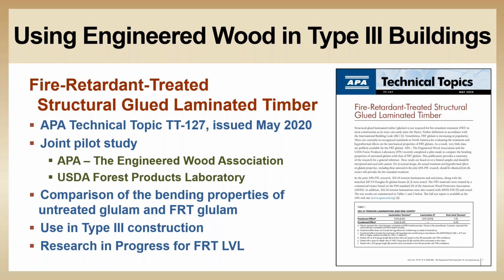Additionally, I'll note the test of FRT LVL is currently in progress. So if you get a request for FRT LVL, you should handle it the same way you would handle FRT glulam, and recognize that the reductions should be provided by the specific treater. And it's also important to remember the LVL does not qualify as heavy timber.